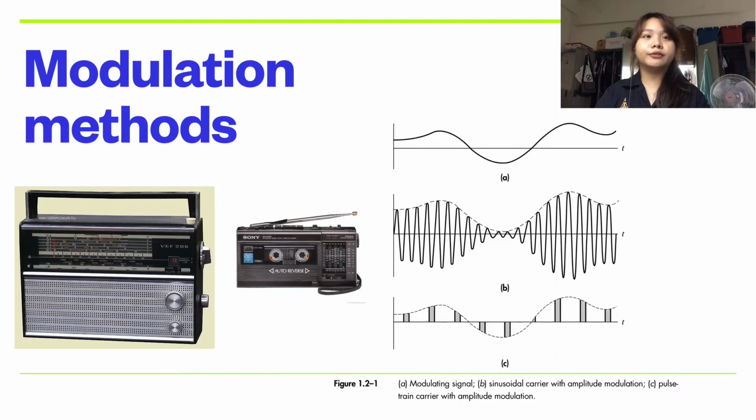Modulation involves two waveforms, a modulating signal that represents the message and a carrier wave that serves the particular application. A modulator systematically alters the carrier wave in correspondence with the variation of the modulating signal. The resulting modulated wave thereby carries the message information. We generally require that modulation be a reversible operation, so the message can be retrieved by the complementary process of